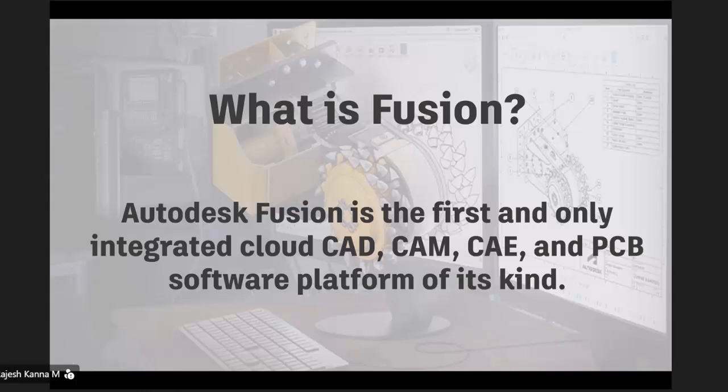We do have CAM manufacturing, starting from 2-axis lathe, 3-axis milling, 4-axis and 5-axis milling, and we also have 2-axis plasma and laser cutting for 2D cutting. Then we also have turn-mill compatibility for different machines. It can support multi-axis or multitasking machines.